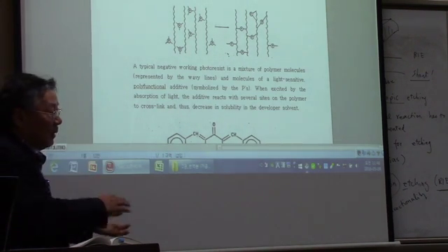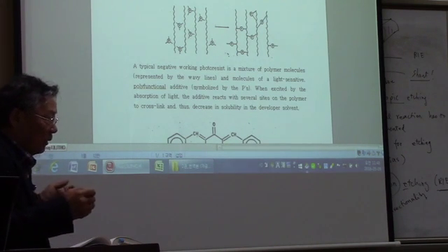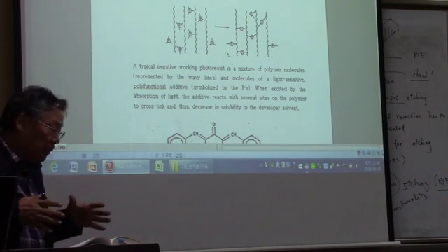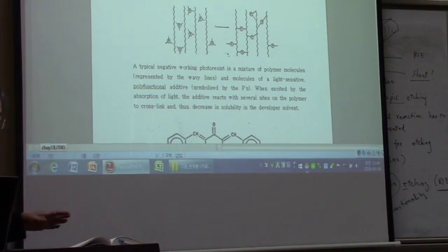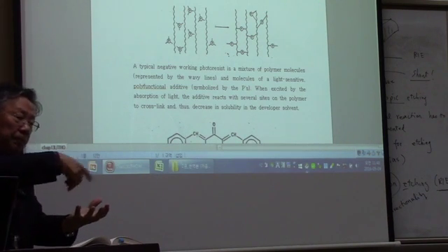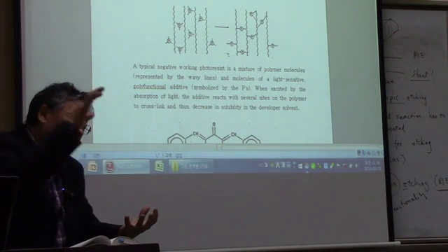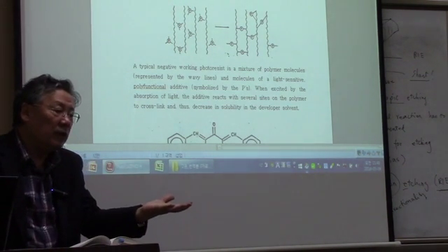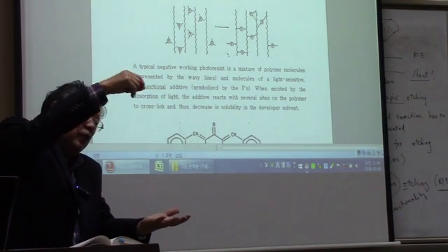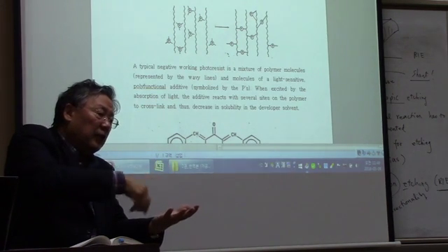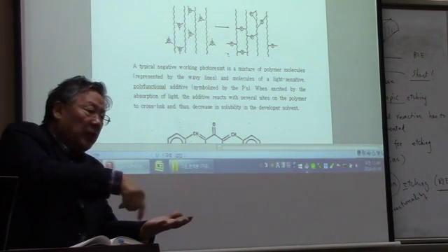Well, that's just to make it liquid with a certain viscosity. Because the way we put the PR photoresist on the substrate is by spin. Okay, you have a rotating thing, spinner, and then you place your wafer to be coated with the photoresist, and then a little bit of photoresist is going to be dropped at the center of the spinning table.